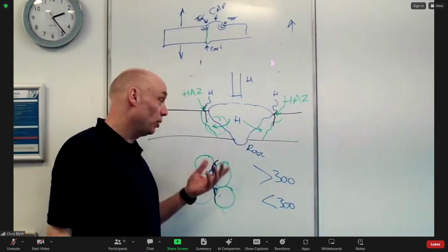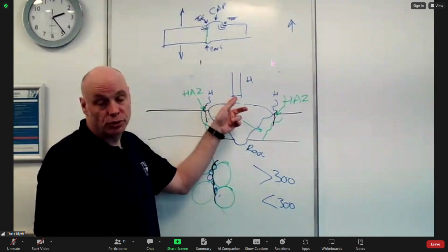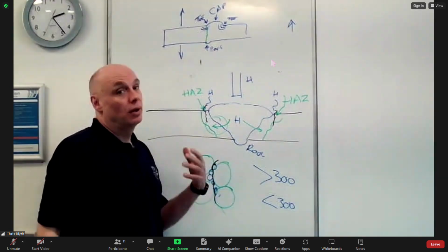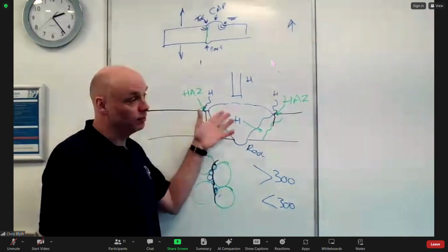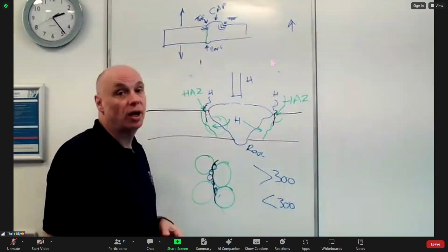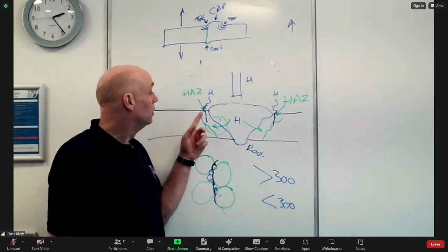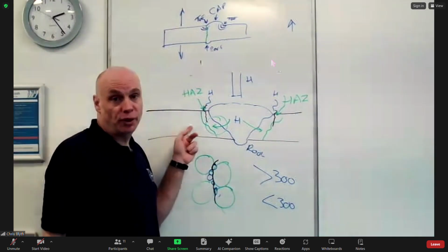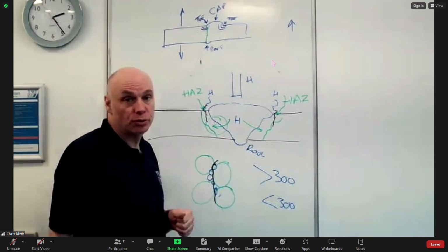Okay. But again, it's going to be dependent on lots of factors: the type of welding consumable used, the susceptibility of the material. And obviously we put control measures in to reduce the effects of this hydrogen uplift. Okay. And usually, like it says there, carry out NDT up to 48 hours after the weld has been completed to look for any hydrogen-induced cracking.